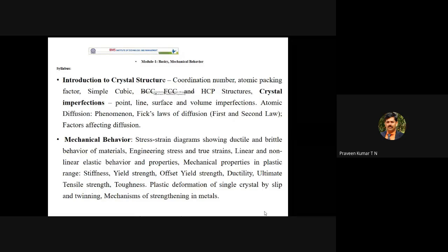Whatever amount of heat is transferred from the coffee or tea goes through the walls of the thermal flask. In the similar way, in the closed mold process, heat lost by the molten metal goes to the atmosphere through the mold wall. There are some cases where there may be very fast cooling, and the molten metal will be cooled fast. If you use a metal mold, metals have more thermal conductivity compared to ceramic material, so the cooling rate is very fast.